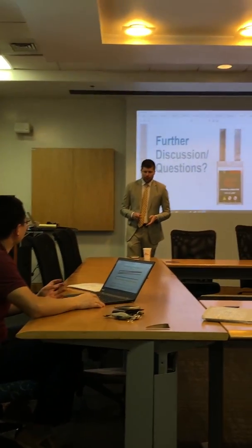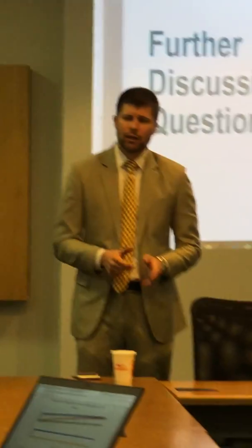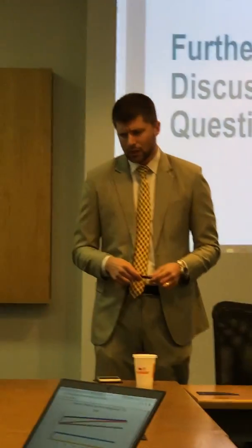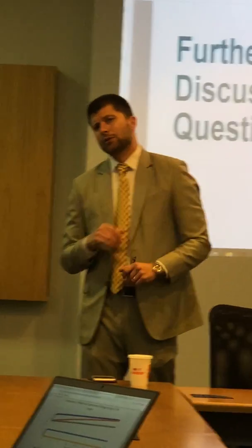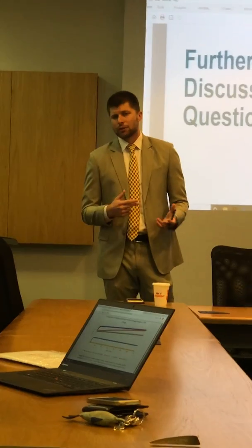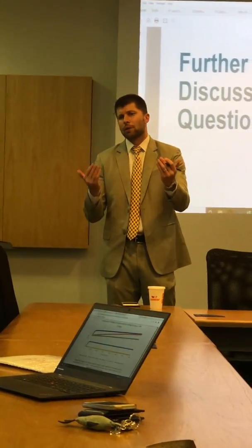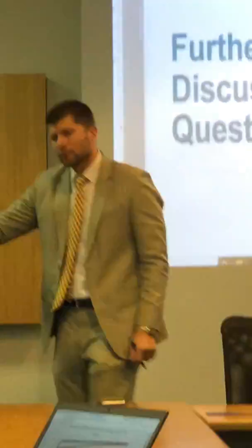Well, what happens, Dr. Yu, is because your ions are lithium ions, they're able to essentially reduce and oxidize deep into the electrode material during a charge and discharge. So you have both the Faradaic and the non-Faradaic reactions happening at the same time. During one charge cycle, let's say this ion, let's call him Bob the lithium ion, he may act Faradaically, he gets discharged.